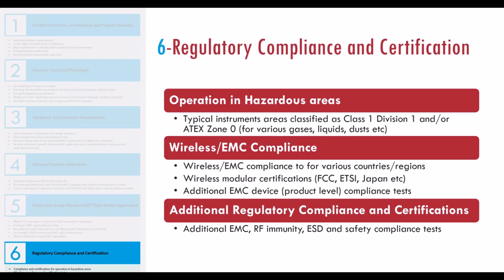But in addition to that, since you are integrating our module into a product, you will be required to run additional tests, such as FCC subpart 15, which is called an unintentional radiator test, the way you just demonstrate that you're not negatively affecting the operation of the module, which already has FCC approval or EU approval. Same in Europe and Japan.